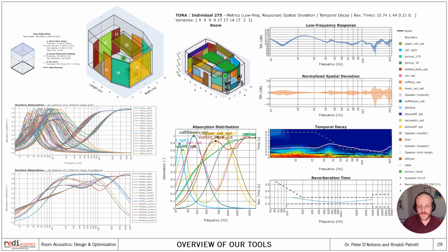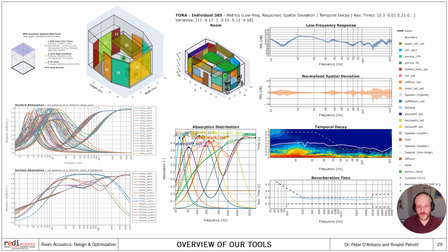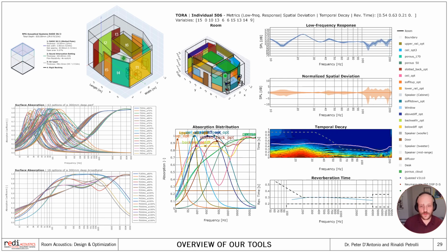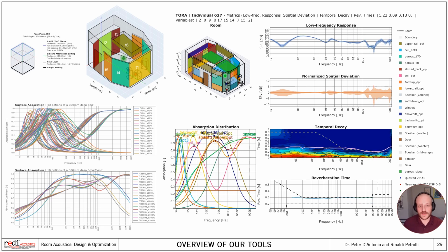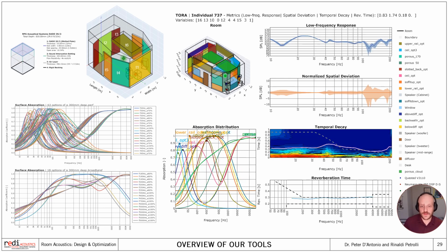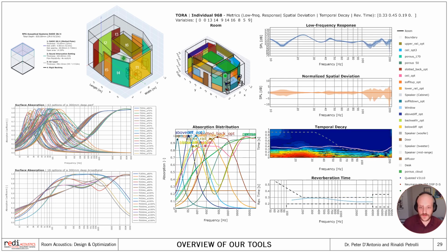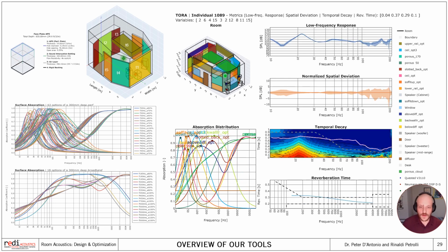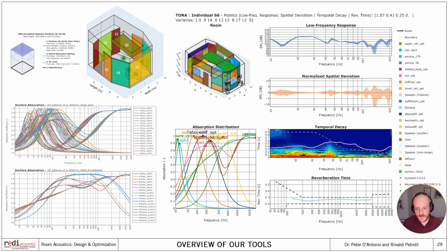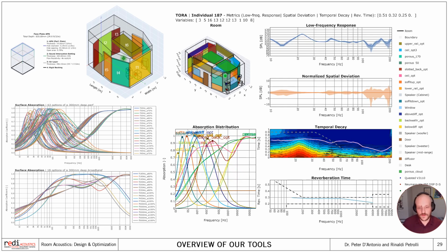So enter TORA, standing for Treatment Optimization for Room Acoustics. And this is the most complex optimization tool that we have because it takes into account 4 different metrics simultaneously. Here, we are optimizing not only the low frequency response and its spatial deviation, but also the temporal decay at low frequencies and the reverberation time at mid and high frequencies.